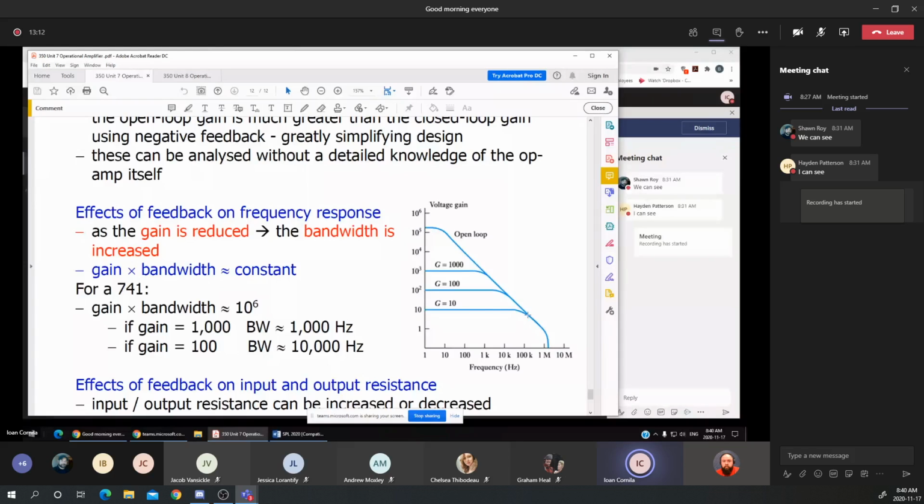in applications. As a suggestion, you may use the op-amps in your capstone project or any other projects. I'm suggesting to use a lower gain to have a wider bandwidth. The maximum bandwidth I mentioned is just a bit above 1 megahertz, but for 1 megahertz, I don't have too much gain.